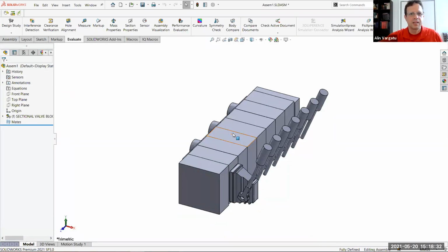We have 100 meg. Let's purge configuration data. Let's do all kinds of crazy things. No, don't do that. SOLIDWORKS simply goes in the file and extracts only what it needs for that specific moment in time. So in this case, for this assembly, it just went to the big file and picked up only the configuration body data for this configuration. So very smart, very efficient.